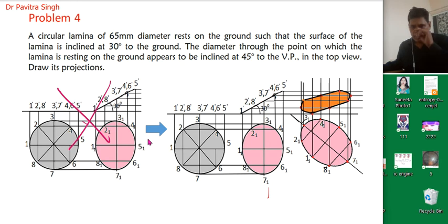So now I will try to solve this problem here. First we will draw the XY line, meaning a reference line. In each and every problem we need to draw this XY line. This is the reference line which connects the vertical and horizontal planes. Now, as per the given conditions, we will solve this first, here to here. Then we will consider this condition, then this condition.